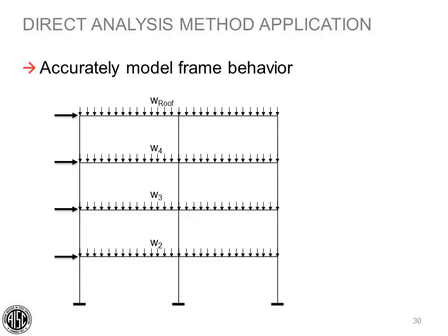I mentioned leaning columns. By leaning columns, I mean gravity columns that support gravity loads but are not part of the lateral load resisting system. These are gravity columns that lean on the lateral system for stability. This is something I see missed a lot when someone is analyzing a frame with an isolated 2D model as shown here. They often forget to add the effect from all the gravity columns that rely on that frame for support and work to destabilize the frame.